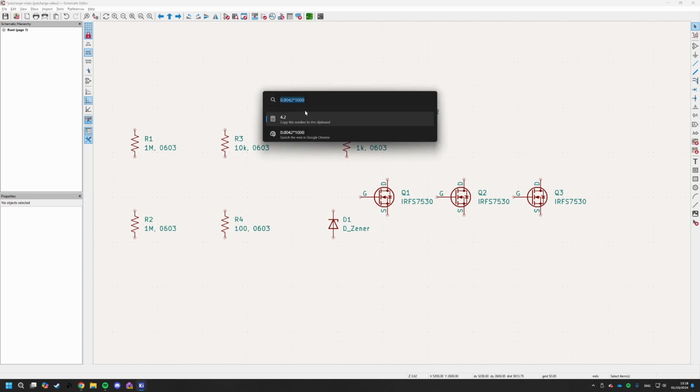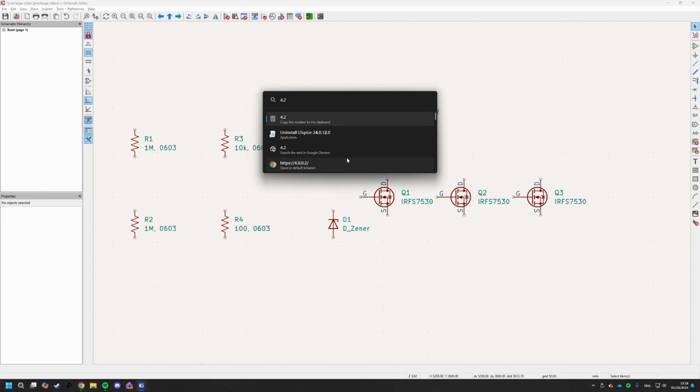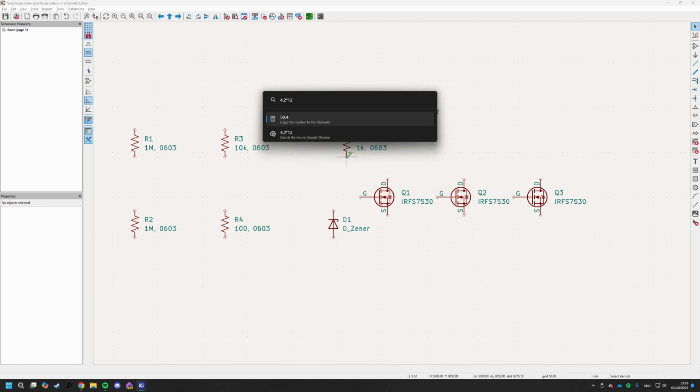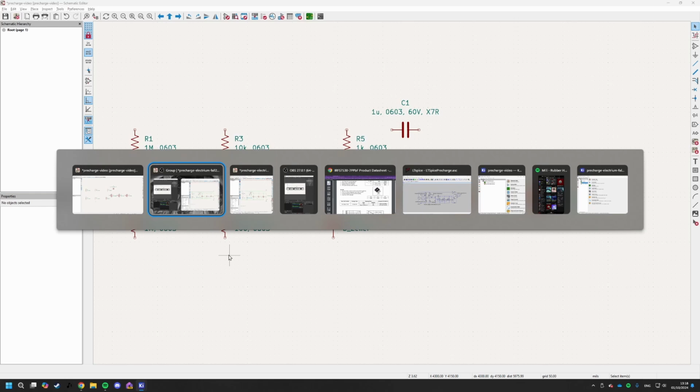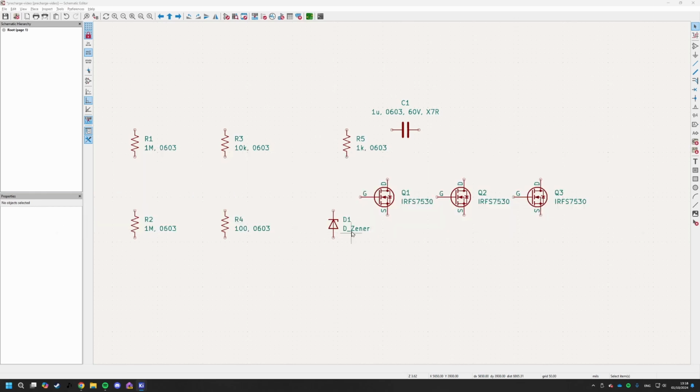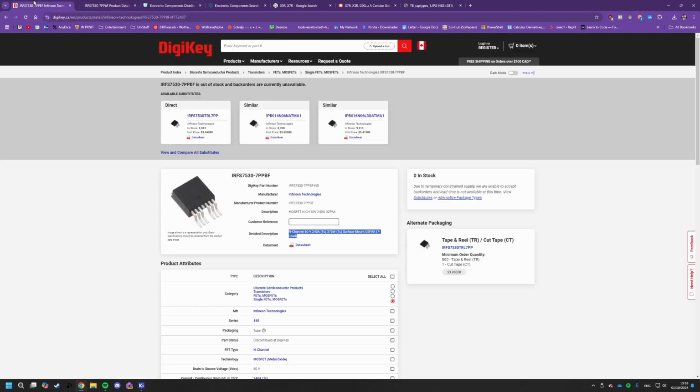So from this current, and multiplying it by the voltage of the Zener diode to obtain power, we'll get 50 milliwatts. So to just be safe, we can multiply this value by an extra 33% and get 70 milliwatts. Cool.